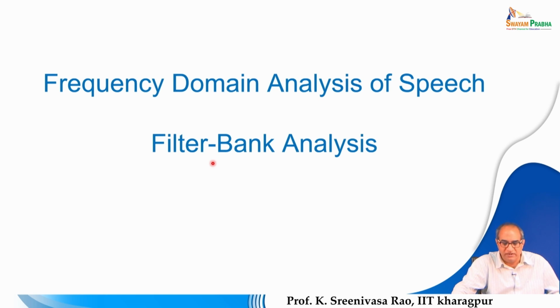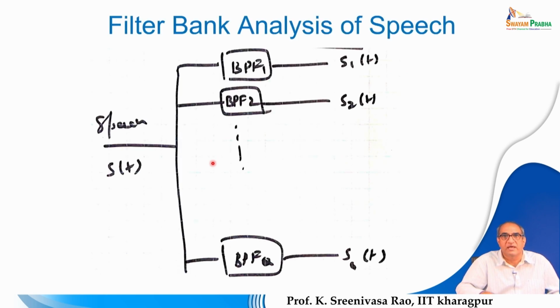The idea in filter bank analysis is this: if you want to analyze the frequency domain content of speech, we know that speech is a wideband signal. The speech frequencies range from 0 to 20 kilohertz, but most of the energy is concentrated in the lower range, up to 4 kilohertz or at most up to 8 kilohertz.